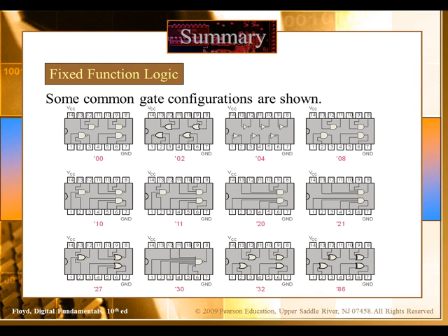Every IC has different logic gates. So since you need NAND gates, you know you will need 7400. Now, how many 7400s do you need when you have 3 NAND gates? You just need 1 IC, because look at this, in 1 IC you have 4 NAND gates. Even if you need 4 NAND gates, you can work with only 1.